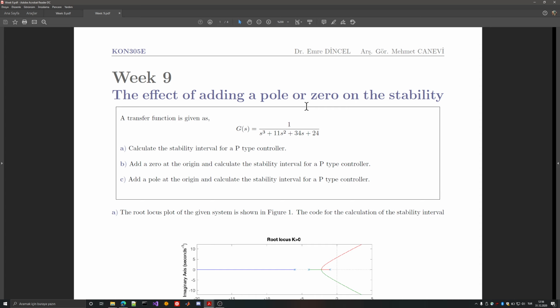For the PID controller, basically, you have 2 zeros and a pole at the origin. You can place the zeros on the whole complex plane at this time, because you have 2 of them, and you have to place a pole at the origin. And that's it. You cannot change the pole. So it has more freedom because you can place more zeros, and you can basically increase the stability of the system, since adding zeros is a better idea than adding poles.